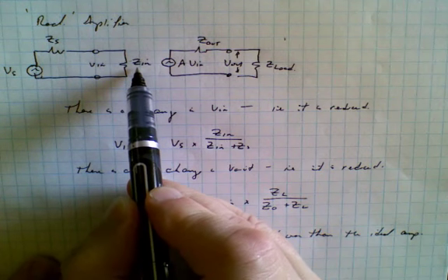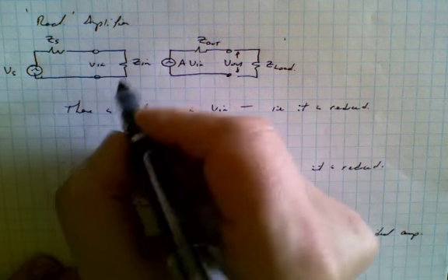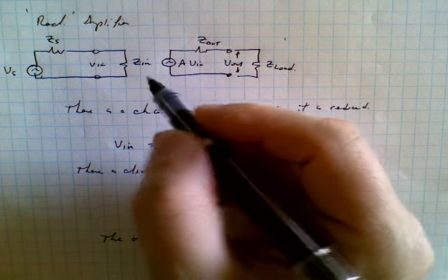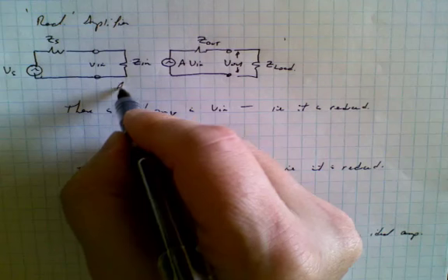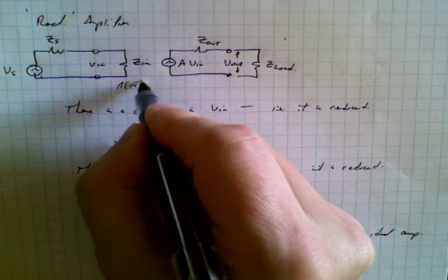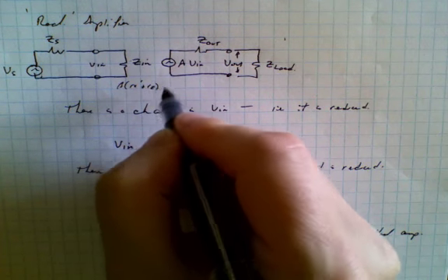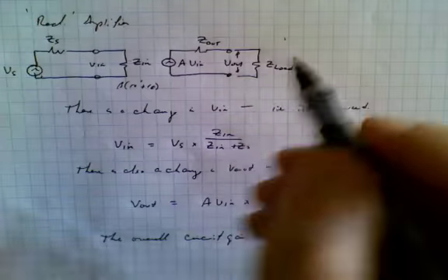And this, remember, this input impedance for a transistor is basically a function of emitter current. Remember, it is beta times Re prime plus Re, and maybe plus biasing components as well.